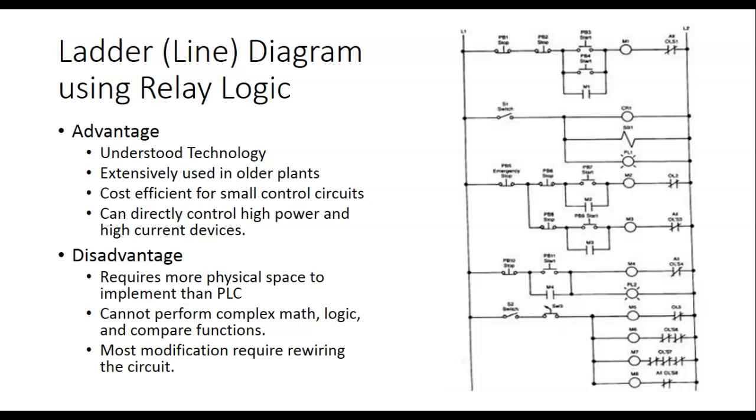I've never been into an application where we can do it with nothing but PLCs. As we look at our manufacturing lines, every module has PLCs, and every module has relays. Because the PLC is not designed to provide a lot of current, but it provides enough current to energize a relay and then let the relay do all your high-powered work.